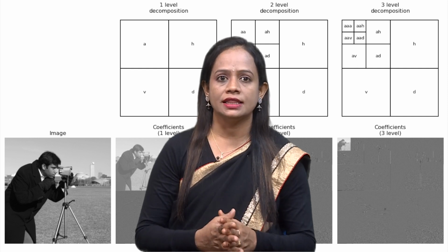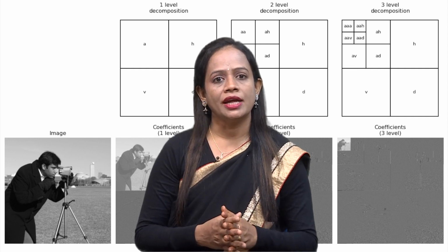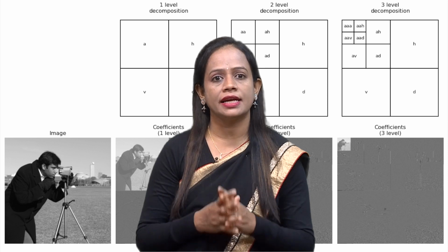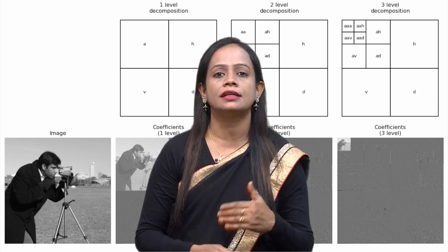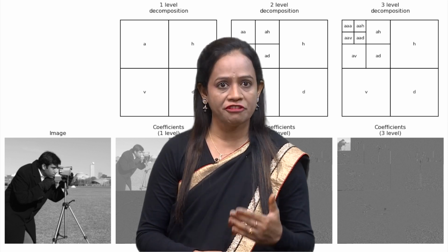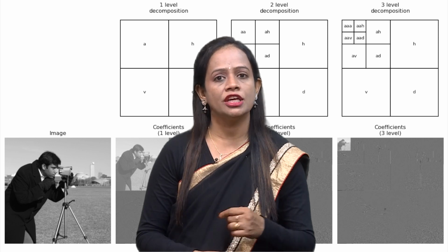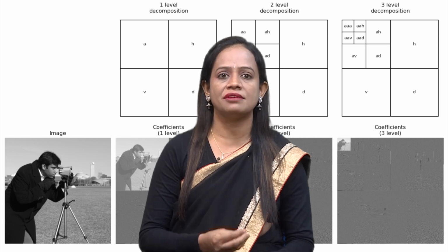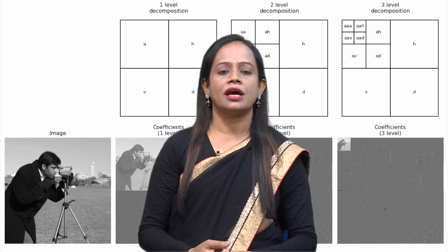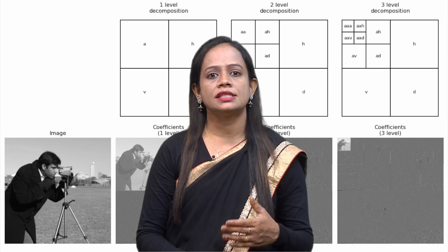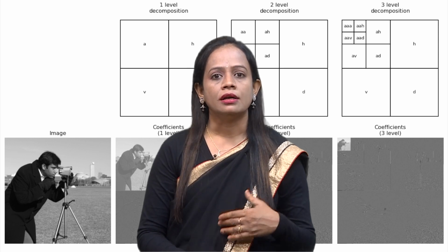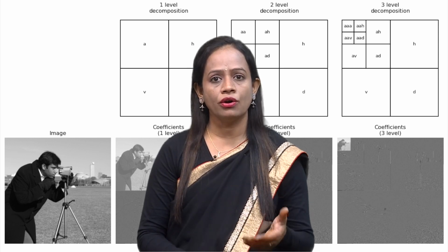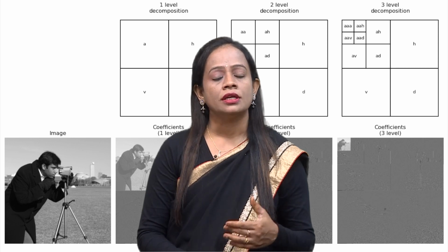The DWT decomposes the input signal or image into multiple frequency subbands, capturing both high frequency and low frequency components. In this method, bior1.3 is the second argument specifying the type of wavelet filter to be used for DWT. In this case, it specifies the bior1.3 wavelet, which is a specific type of biorthogonal wavelet filter.